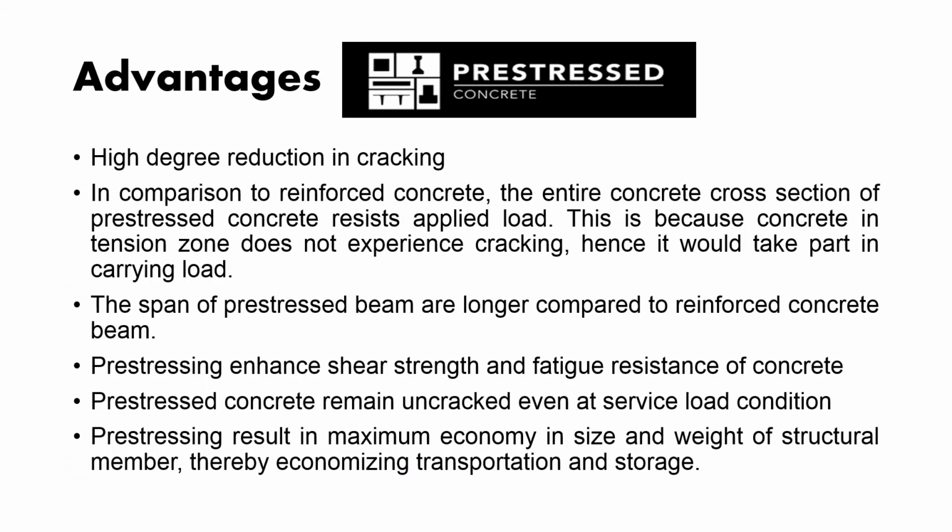So let's look at the advantages. There is a high degree of reduction in cracking compared to normal concrete. In comparison to reinforced concrete, the entire concrete cross-section of pre-stressed concrete resists applied loads. This is because concrete in tension zones does not experience cracking, hence it takes part in carrying the load. And the spans of pre-stressed concrete are longer compared to reinforced concrete beams. So you can design a longer span if you're using the pre-stressed beam.